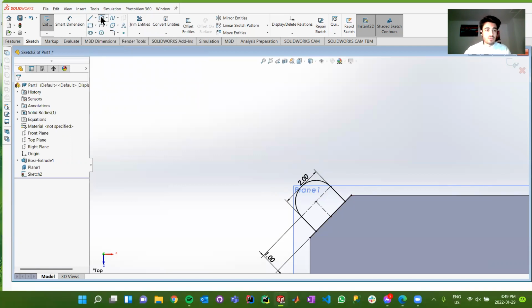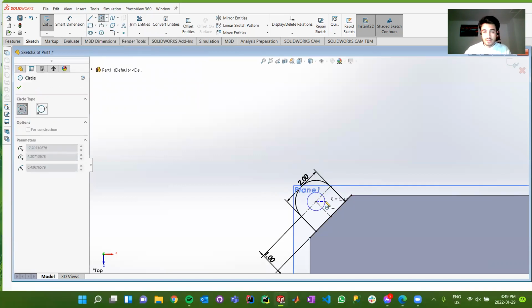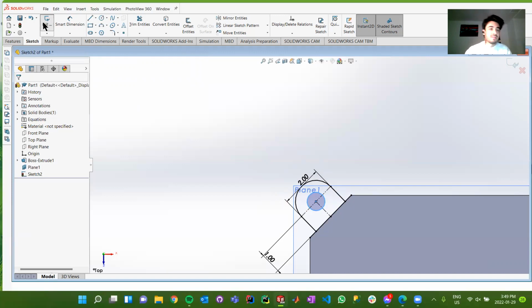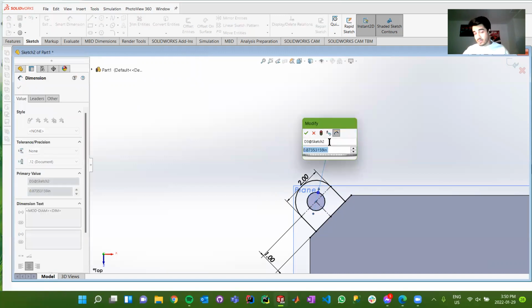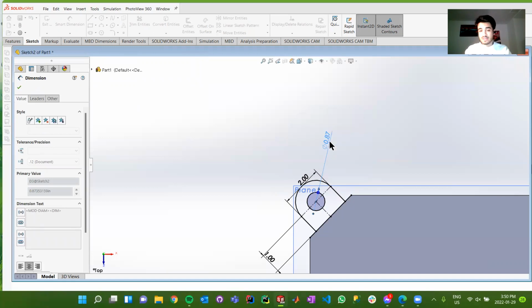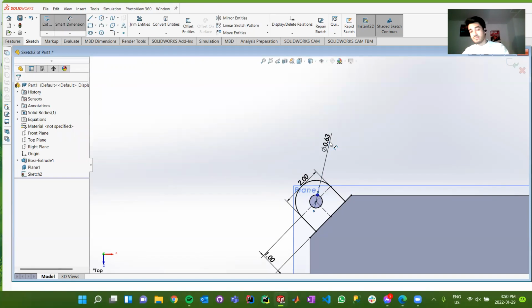So what I'm going to do is I'm going to draw another circle, and I'm going to draw the spacer right here. And this is going to be our bolt hole. And the nice thing about SolidWorks is, in addition to exact values, you can also put in fractions too. So if I do that and press 5/8, you'll see we have this 0.63 hole, which is supposed to be 0.625. We just concatenated or got rid of an extra significant digit.